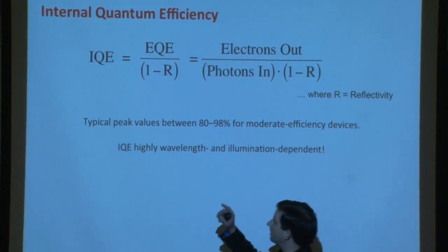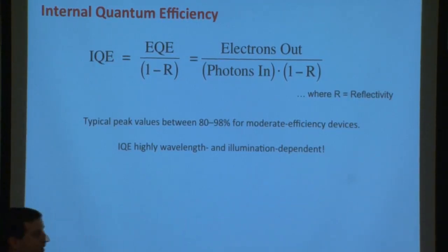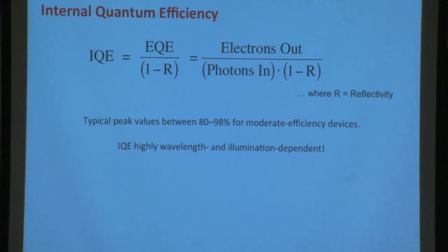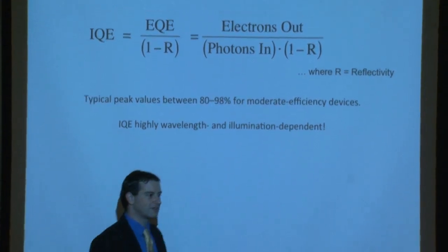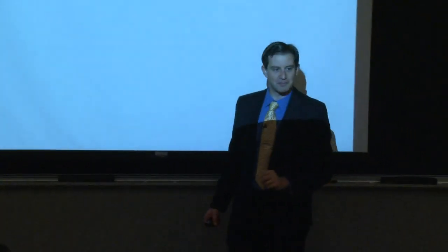Absolutely. So IQE is a function of wavelength. R, reflectivity, is also going to be a strong function of wavelength, because the real component of the refractive index is changing as a function of wavelength. Yep, absolutely.